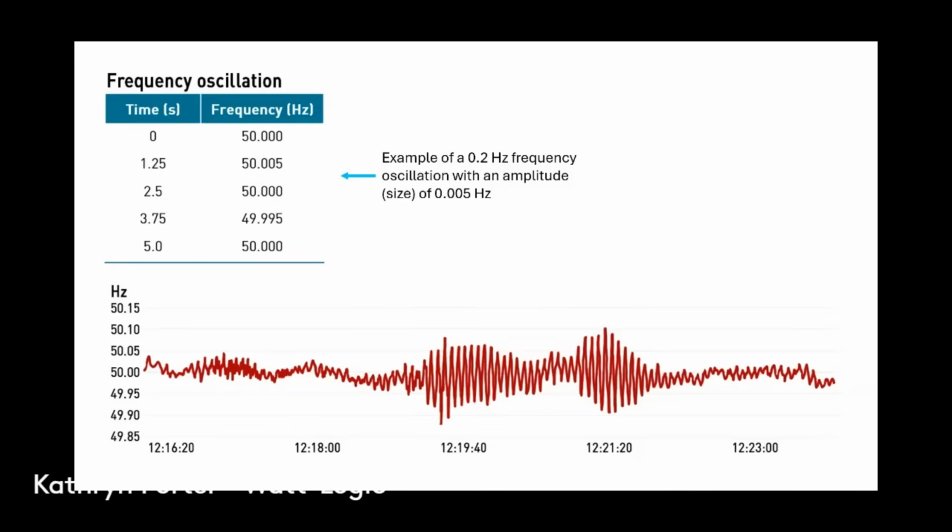And so much of this happened that the frequency fell outside the acceptable grid parameters, and that triggered a lot of conventional generators to trip. So this wasn't a compliance failure, because the frequency had gone below 49.5 hertz, which is the 1% margin that they're supposed to work with. And so you'd expect that once you go below that level, you'll start to get disconnections. And in fact, that's what happened.